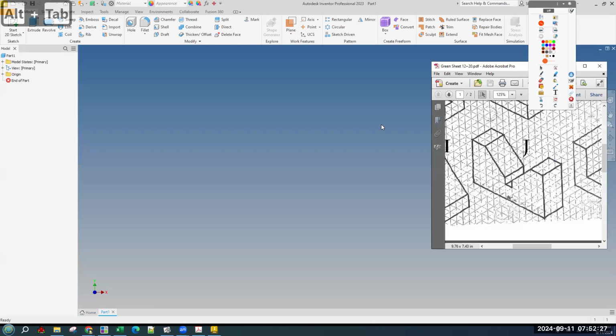All right, so part J, we're going to do it a different way. We're going to use all line tools. We're going to use a line for all aspects of this to make a single closed loop sketch, our 2D shape. That's this shape. Once that's closed off and fully constrained, we'll just extrude it 3. It'll be a single part feature. Obviously, it's a single part file.